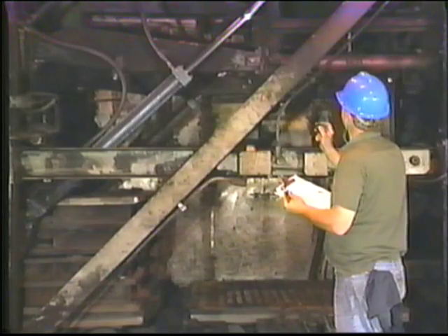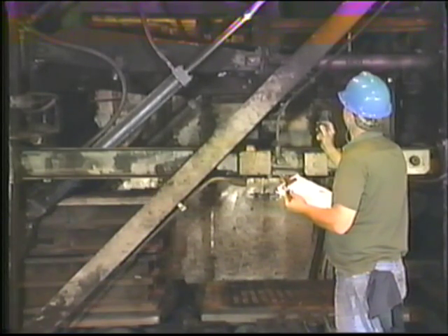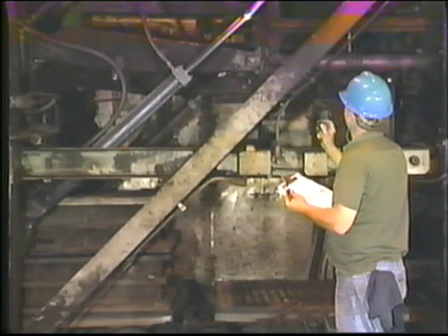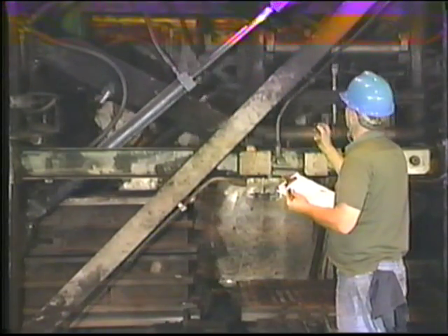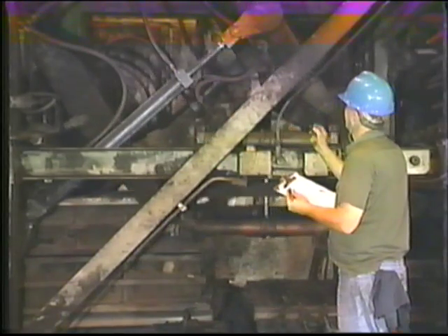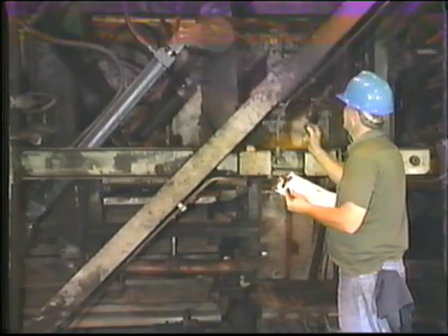Since excessive leaking past piston rings reduces flow, one indication of leaky rings is reduced speed. You can identify pistons that are bypassing fluid by carefully measuring their speed at a particular pressure and comparing it to the speed at which they should be operating.